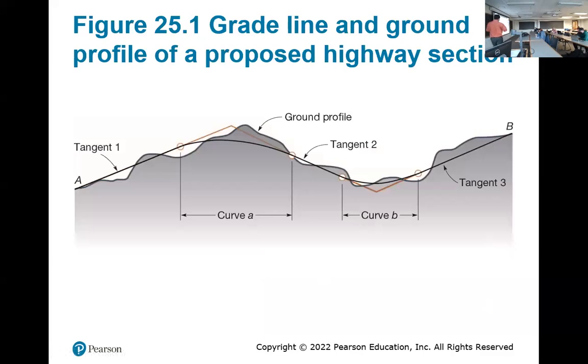If you took that saw and cut it through where your roadway goes, the existing ground kind of undulates. It goes up and down. We took a look at some of the contours and identified where the low spot was, and that's where I hope you put your detention pond. Hopefully you set aside some area for the recreation, like I said. But most likely, the detention pond would be somewhere in this area.